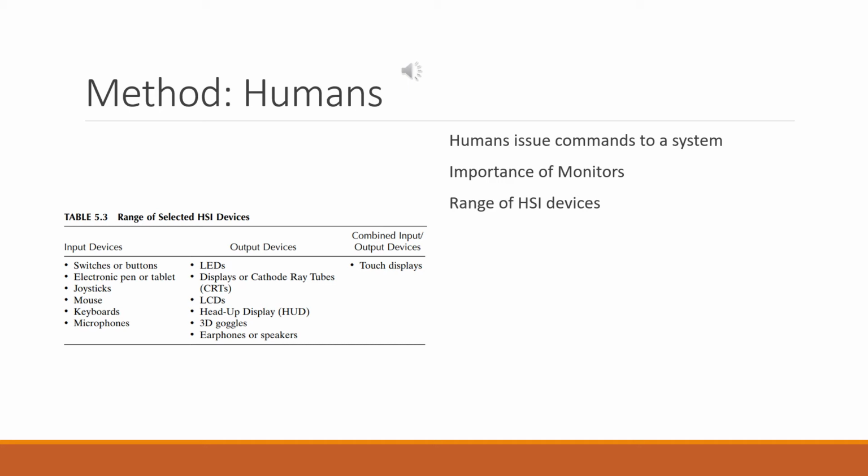Monitors take on a variety of forms, including computer screens, liquid crystal displays, light-emitting diodes, printing on paper, and meter dials. The range of devices used for interfacing with systems are shown in Table 5.3. Test engineers must consider that each and every interface device connected to the system may introduce a certain problem, distinctive to the given device. For example, switches and buttons may typically introduce timing errors or wrong sequence phenomena. Keyboards may introduce text string errors, or a display may show incorrect information.